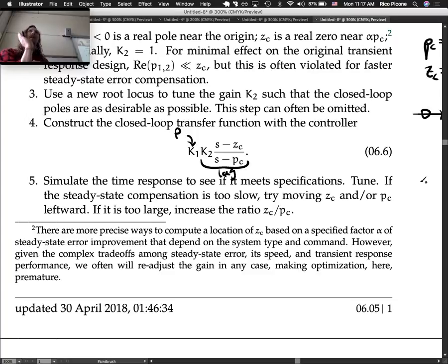So say you want that angle to be 30 degrees or whatever. You can measure the actual angle, maybe it's 20 degrees right now. You'd like it to be 30. You compare it to the reference. So there your reference is 30. The actual feedback output is 20. You take that error, the difference, and you feed it into your controller.